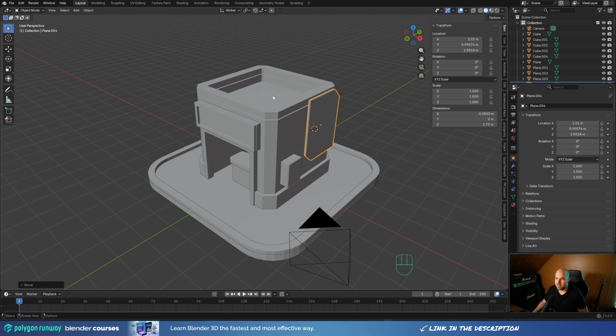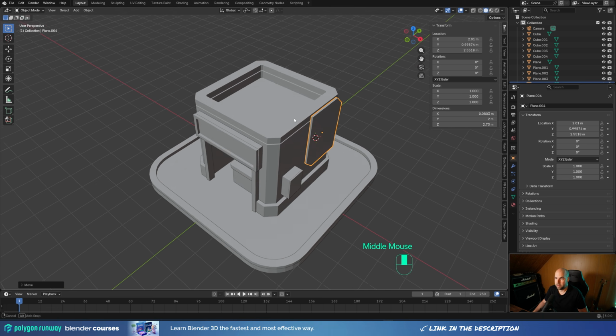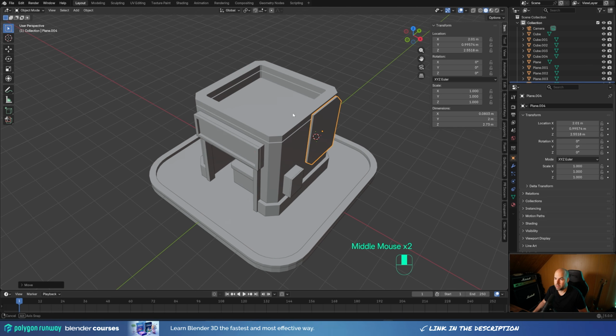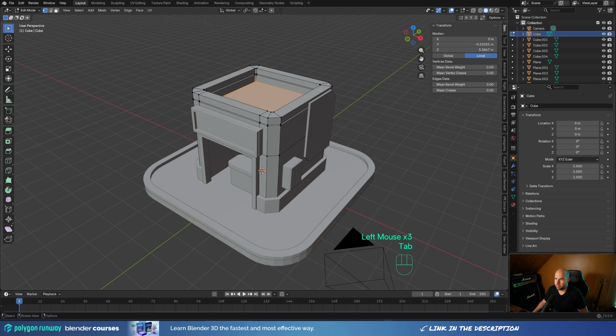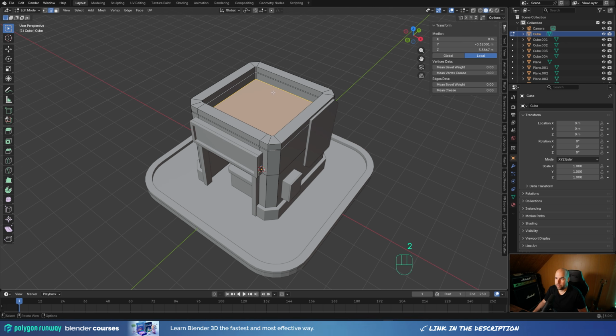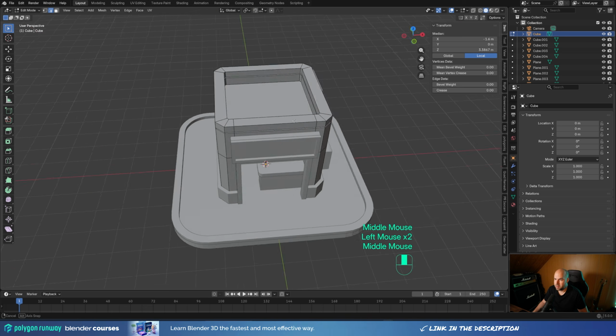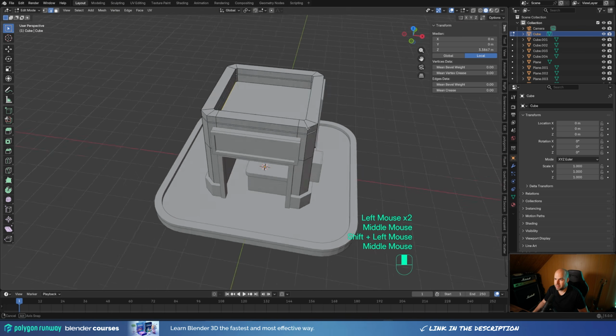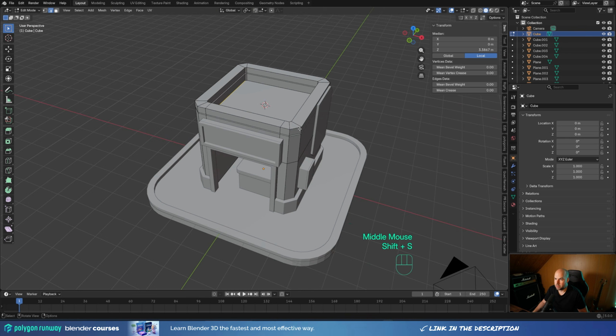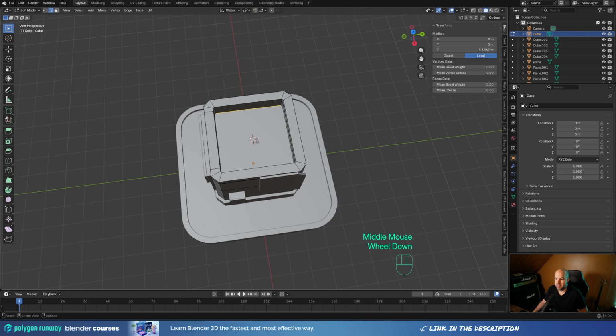And finally, let's block out like a ramen bowl right here on top of the building. There will be like a decoration that I want to make there. So let's select the building, tab into the edit mode, and now I'll press 2 for edge select and select these two edges on the opposite sides and hold Shift S and snap cursor there. So this way I know I'm placing it in the middle.